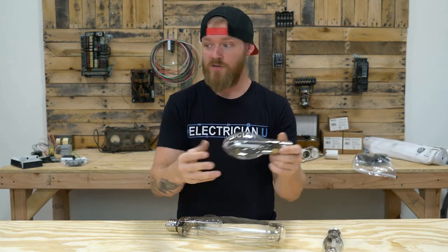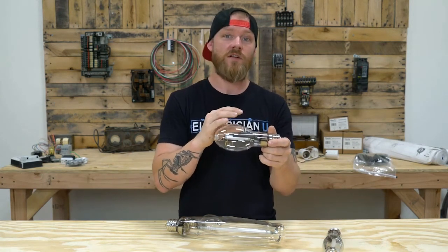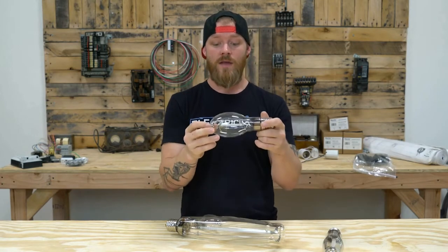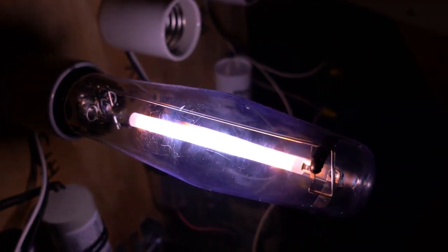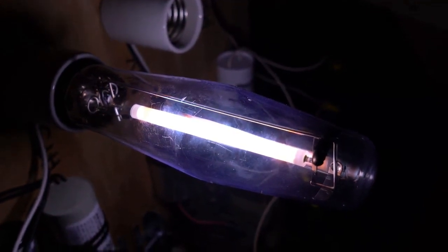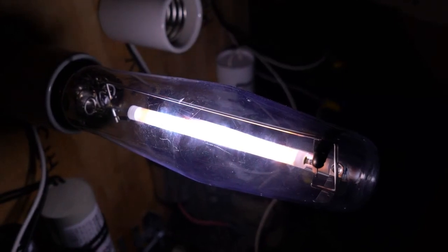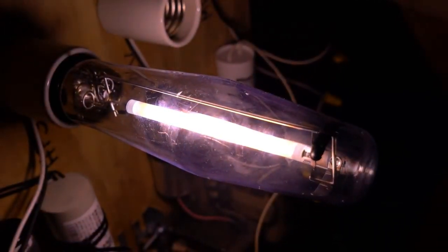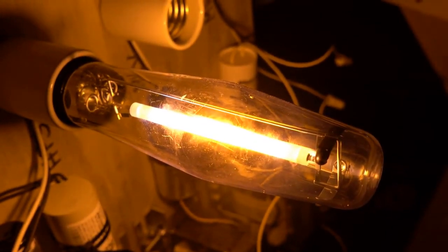The first one is mercury, just like all these other types of lamps. That mercury gets to a certain temperature and it starts to vaporize into that arc stream, and the sodium does the same thing, but the mercury is a little bit lower temperature when it burns, so it burns first. And then once it gets up to a certain heat level, then the sodium starts to burn. So you'll start to see when this thing ignites that you've got this baby blue color once that mercury starts to ignite. And then once the sodium starts to ignite, you'll see it shift to much more of a yellow color.